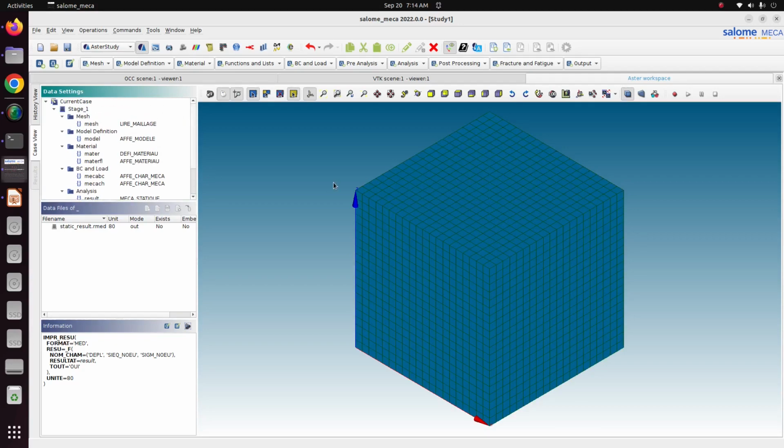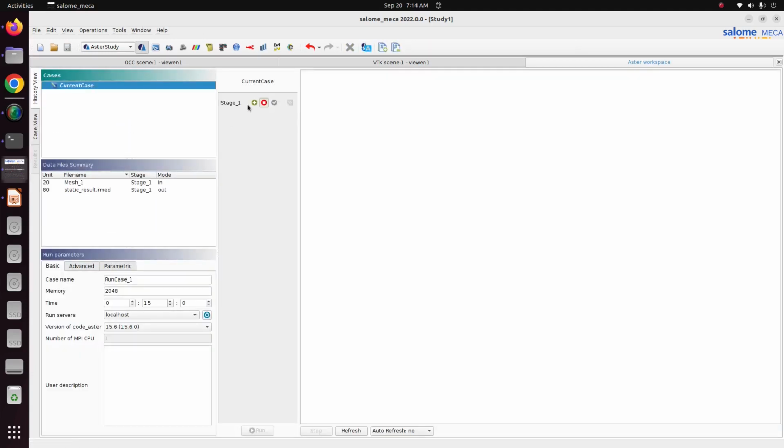Then we just go for solving it. So just save this file. I have saved it. Just go for history. So here just press this plus button, then this is keep result. Just click this one. Now here we just want to run it. To view a message file, just set auto refresh to 5 seconds. Just run it.